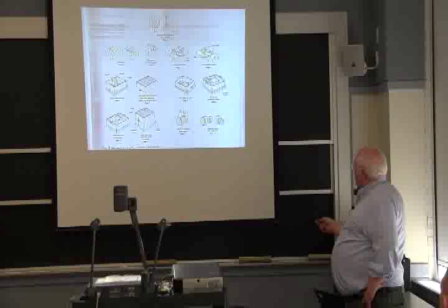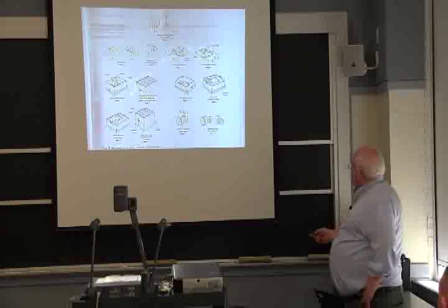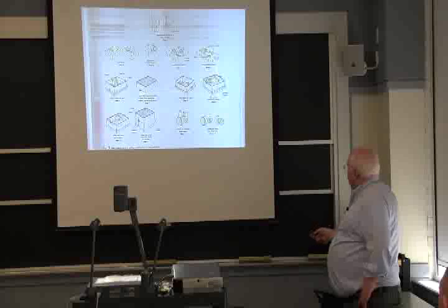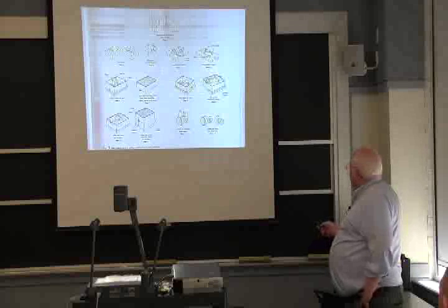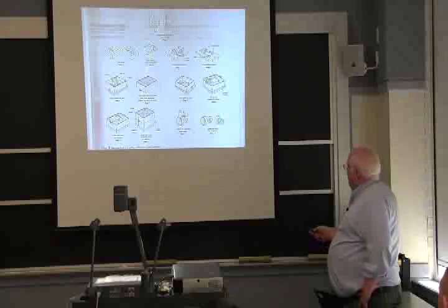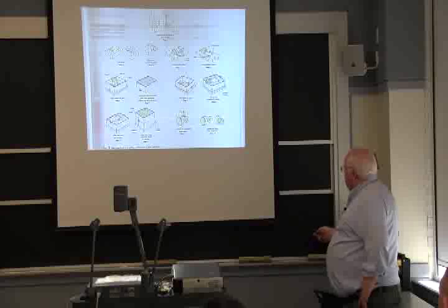There it says cope and drag. And you'll make two half parts, and you'll make a cavity in the sand like this. You'll make a cavity in the sand, and then you'll put the two parts together, one on top and one on the bottom. You now have a cavity the shape of your core halves, and then you pour the metal in and you make your part.